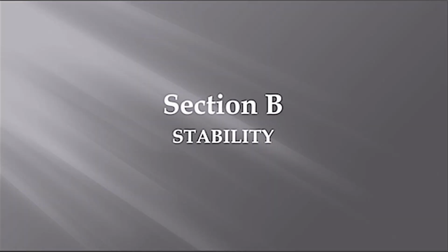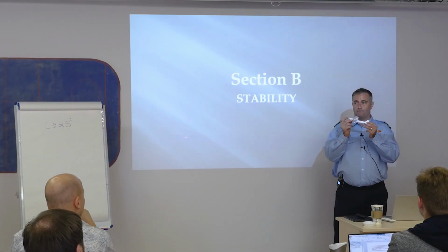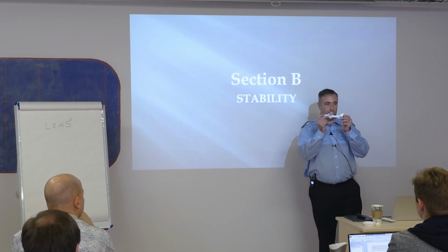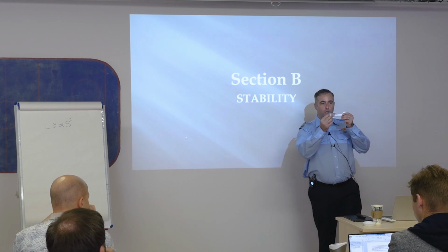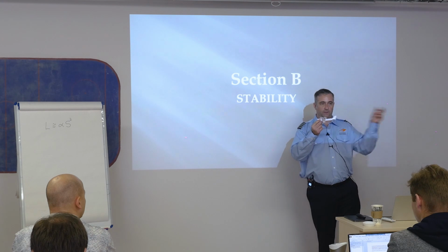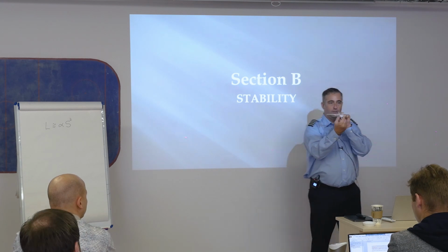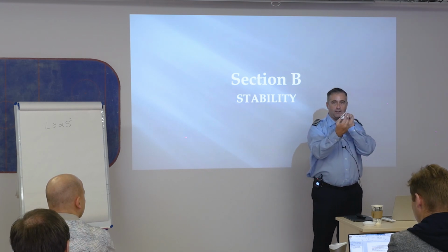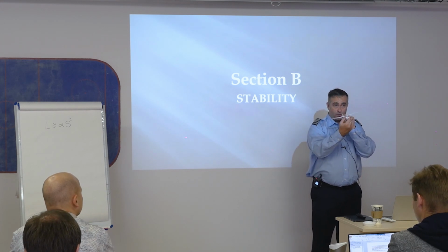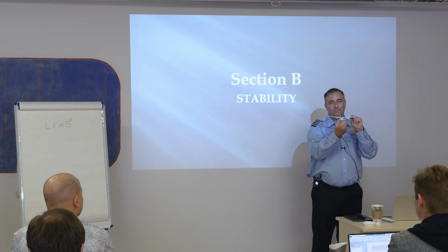We were talking about one axis of flight earlier, correct? You guys remember which one that was? The axis of flight? Longitudinal, okay? Remember, that was a straight line through the nose and all the way back to the tail. And that describes the banking motion of the airplane, right? Or motion that's caused by the ailerons with some rudder input.